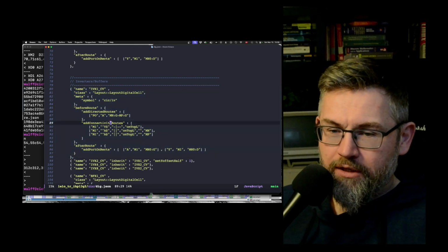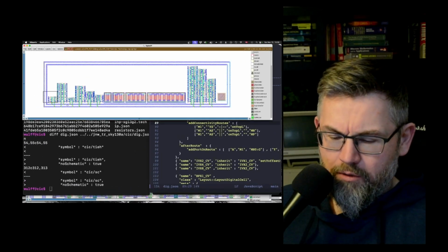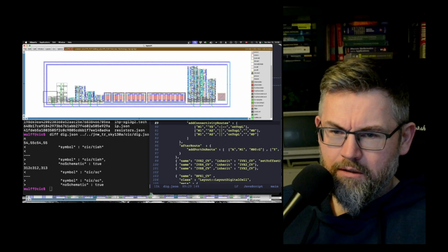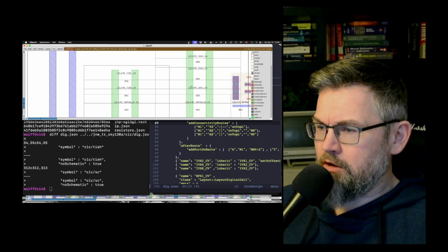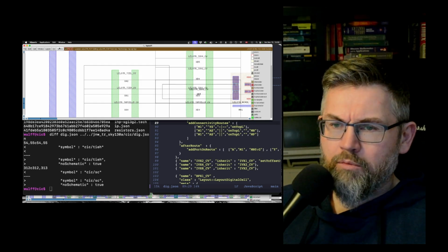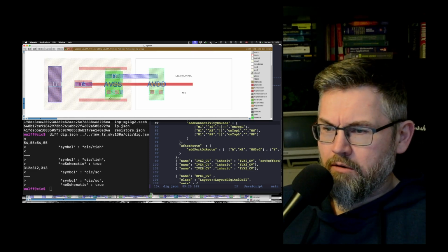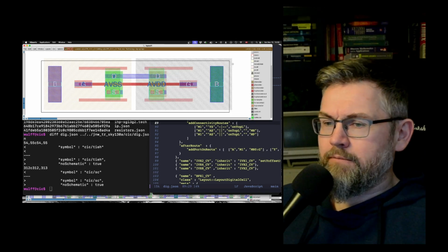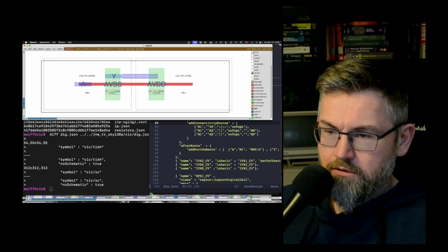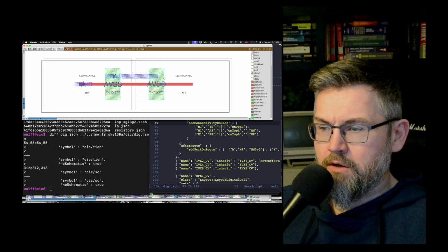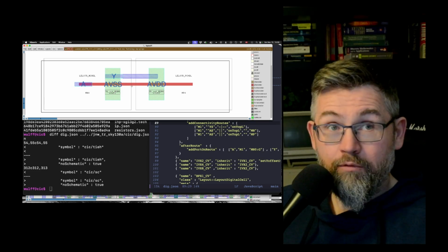And to illustrate how this works, let's go into Magic. And I think somewhere here should be the inverter. IVX1. Let's open that up. Cell, down hierarchy. Okay, this is the inverter. Actually it consists of two cells. Let's just show that. So it has a PMOS and NMOS. And then there's a routing that happens for the Y and for the gate.